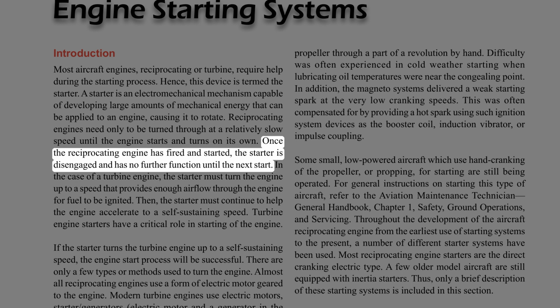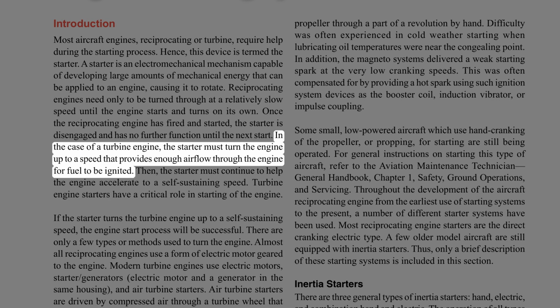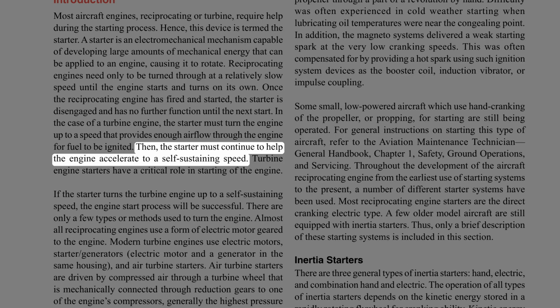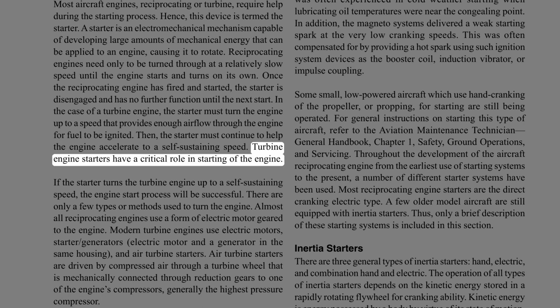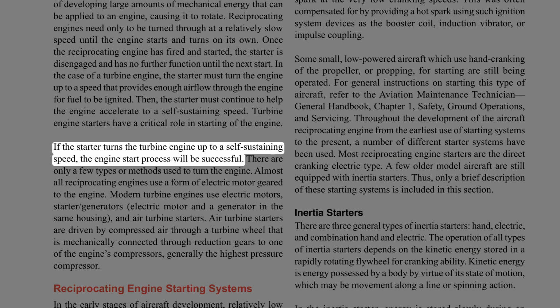In the case of a turbine engine, the starter must turn the engine up to a speed that provides enough airflow through the engine for fuel to be ignited. Then, the starter must continue to help the engine accelerate to a self-sustaining speed. Turbine engine starters have a critical role in starting of the engine. If the starter turns the turbine engine up to a self-sustaining speed, the engine start process will be successful.